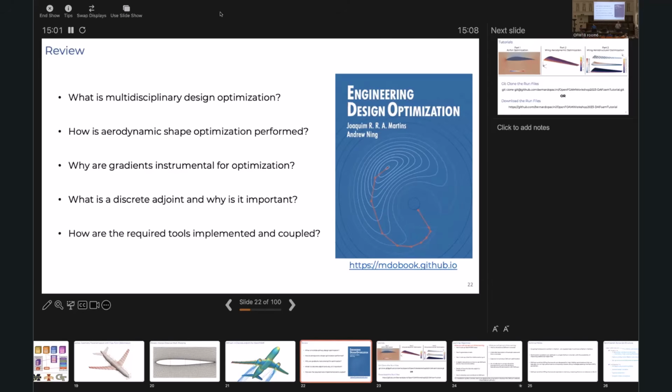We do a matrix-free approach, yes. So for DAFoam specifically, we don't build the whole Jacobian. We pass what we call the seeds through the optimization without this.